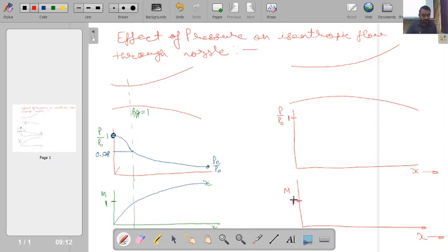Okay, so here what we saw that if the difference between inlet pressure and outlet pressure is very small, so say this is the throat point over here. So I said that if say this is my inlet pressure and outlet pressure over here is some value PE1, and PE1 is very small in comparison to this one. So I will not be having very high flow rate within the nozzle.